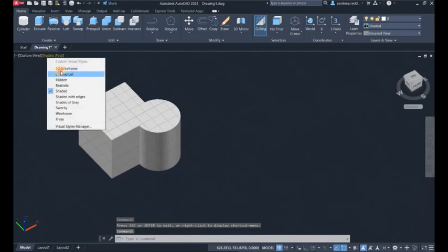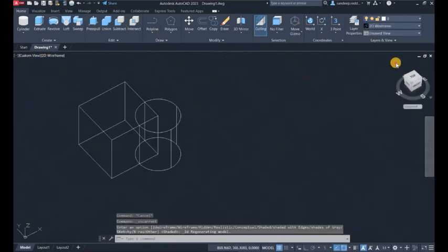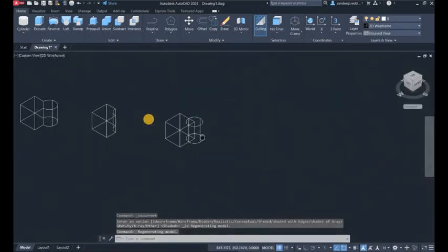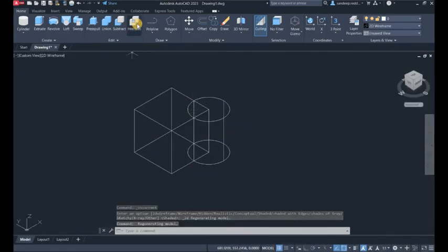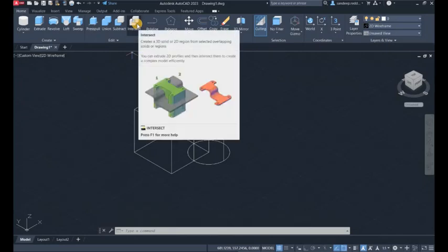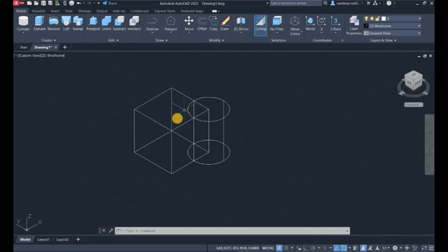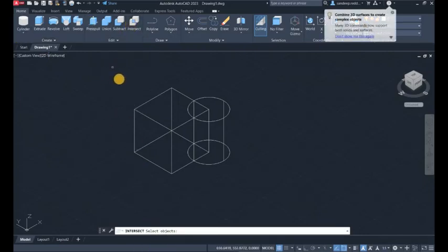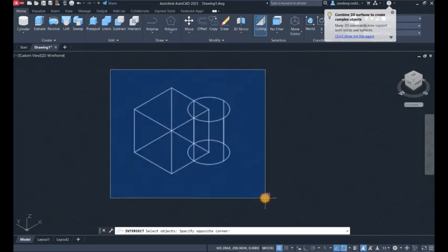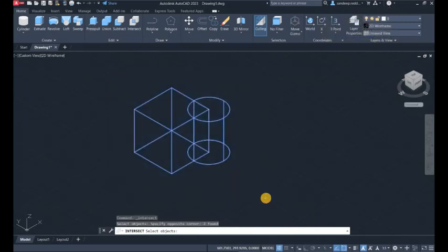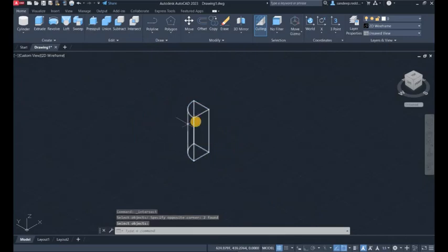Let's look at intersecting objects. What intersecting does is that if you have overlapping regions or solids, it keeps that as the result, whereas the rest is deleted. Here you can see that there's only a quarter of a cylinder which is overlapping onto the cube. So, the start of the intersect command. It's very easy. Select the entire solid for the drawing itself, and then press enter. You see the overlapping region is the remainder, while the rest is deleted.